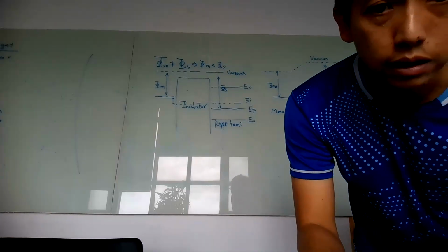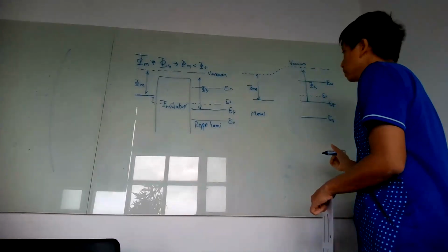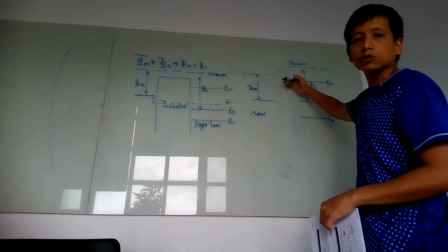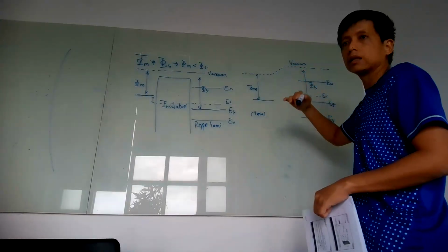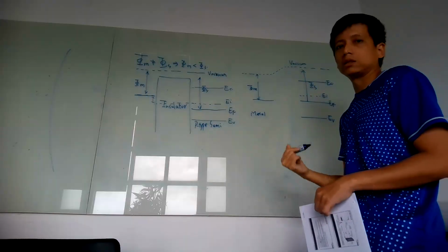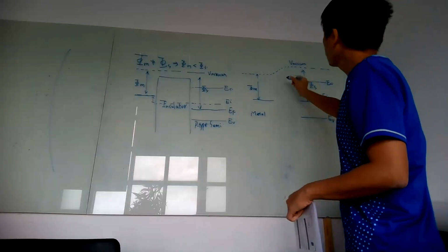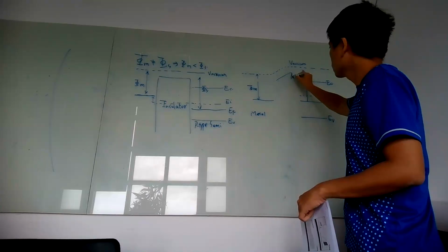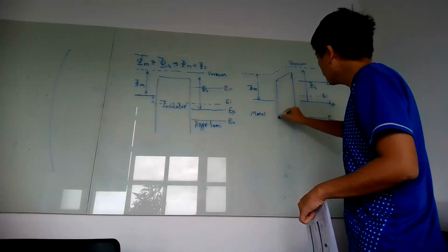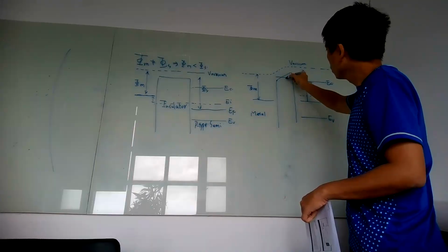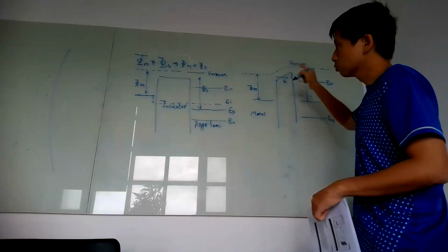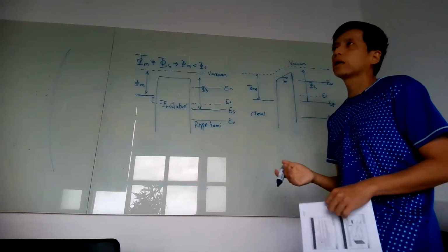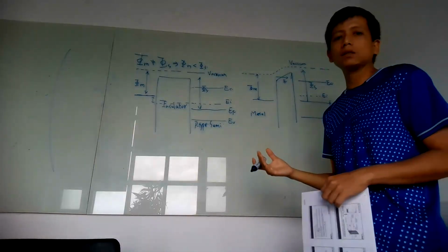Okay, so how do we make the connection in between the two? How does this change in between the insulator and the semiconductor? The idea is that we have a built-up electric field, and all of the band structures should be in parallel together and follow this electric field. So what happens here is we still draw the insulator with the band bending, and we get an electric field from left to right.